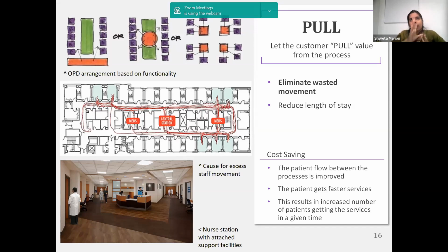Now, for example, you're like a 300, 400 bedded hospital who's doing cardiac, ortho, neuro, and different specialties. Best would be to club these specialties together. Cardiac specialty, you've got about 5 to 6 consulting rooms with its own small nurse station and waiting area. So then everyone just roams around that small box alone. Within that cluster, they will have about 2, 3 consulting rooms, plus maybe your ECG, echo, all that in that place itself. TMT can be provided with it so that they don't have to actually roam around to other parts of the hospital, get their test done, and then come back here.